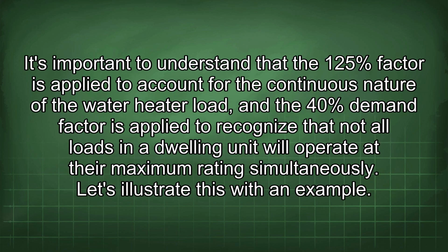It's important to understand that the 125% factor is applied to account for the continuous nature of the water heater load, and the 40% demand factor is applied to recognize that not all loads in a dwelling unit will operate at their maximum rating simultaneously.